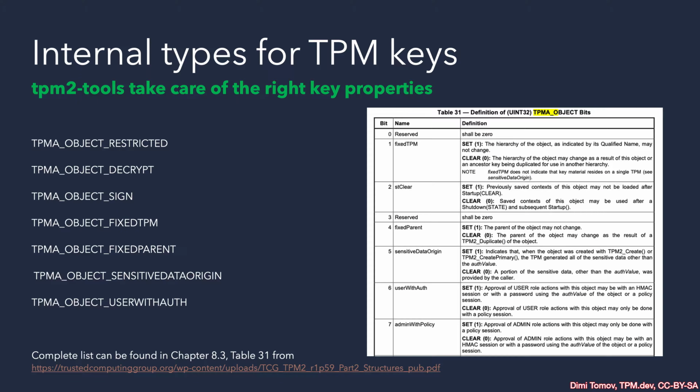We already mentioned some of the supported algorithms by the TPM. This varies between different models and vendors, but there is a minimum that the TPM must provide that is defined by the Trusted Computing Group. Here I have just given an outline of what typically is supported by a TPM. We have a lecture where we'll see how we can check the capabilities of the TPM. Of course, the easiest would be to consult the datasheet, but to be certain, it's best to use some of the internal commands the TPM provide to check what is actually supported.